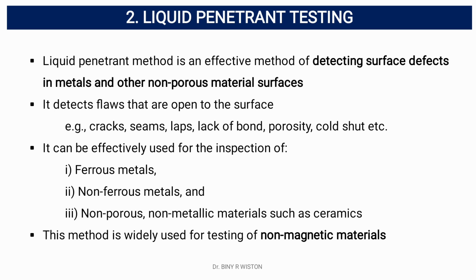Penetrant testing utilizes the natural accumulation of a fluid around a discontinuity to create a recognizable indication of a crack or other surface opening defects. Capillary action attracts the fluid to the discontinuities as compared to its surroundings.